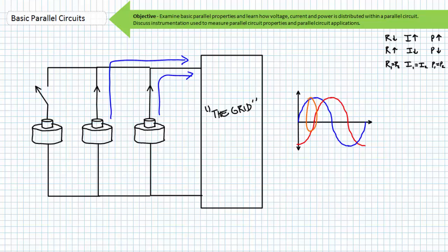Consider a rotor lagging ever so slightly behind or leading ever so slightly ahead of the desired synchronization position. This rotor could suddenly be motored forward or brake backwards at the time of synchronization, often with catastrophic mechanical results. Don't be the dude with your hand on the switch when this happens, because you should know that voltage across two elements placed in parallel with each other should be the same. We'll return to generators, generator synchronization, the grid, and transmission topics in later lectures at the Big Bad Tech channel.